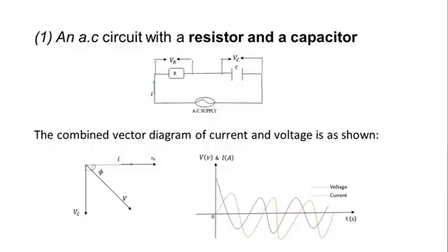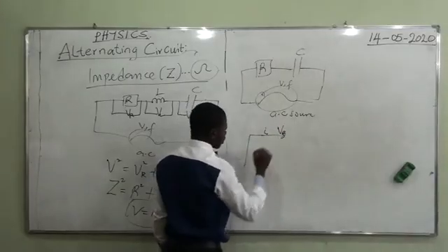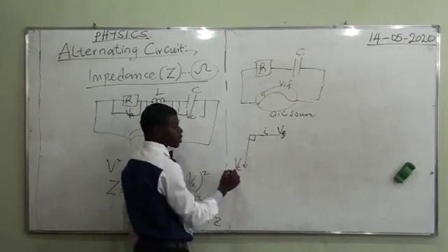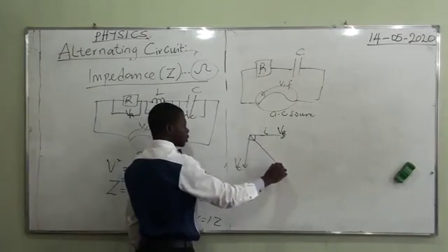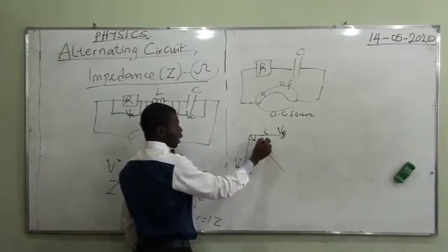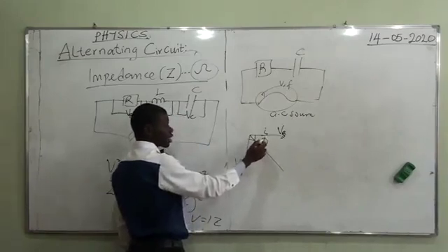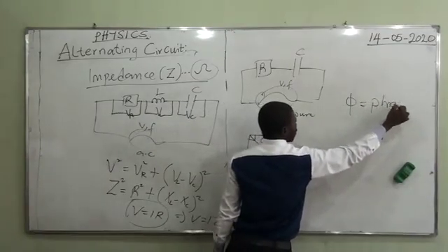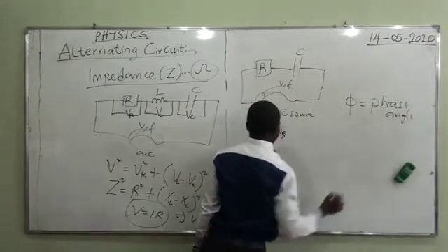So here, on the left side of that chart, you see the phasor diagram. The currents are made to flow in the same direction as the voltage through the resistor, and then you have the voltage through the capacitor. The angle here is 90 degrees. You draw a diagonal, which will later become a hypotenuse, and put an angle here called phi, the Greek symbol, which represents the phase angle.